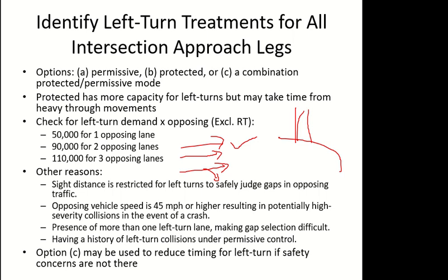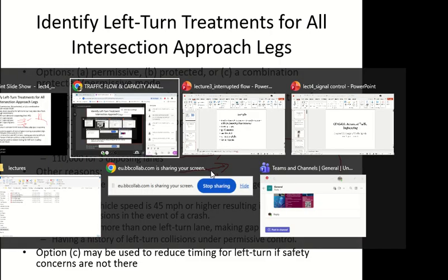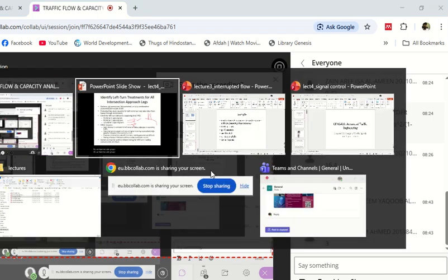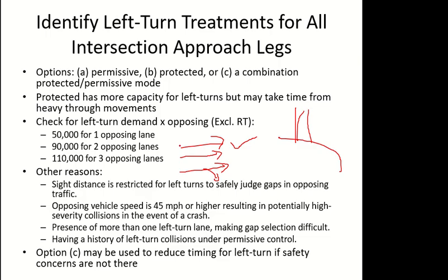No, we have two lane groups. Okay, we have two lane groups. These two are one group, and this one is another, so this is one and this is two. When lanes have exactly the same movement, they are in one group, because their capacity will be the same. This is the idea behind the lane group.